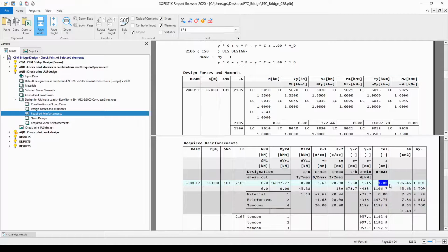So basically the internal criterion is to increase the reinforcement until we reach the capacity of the cross-section being equal with the acting external force. And what we can see in this case is that in the top layer, in the left layer, in the right layer, also in the torsional reinforcement layer, the minimum amount of reinforcement that we had defined was kept and used.